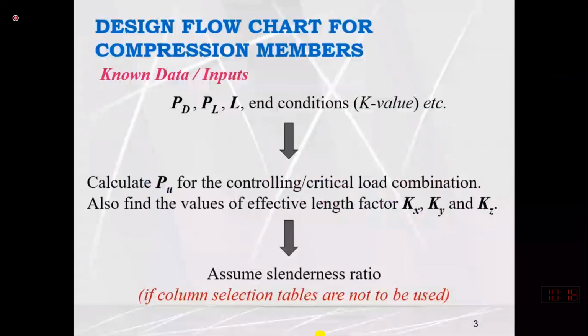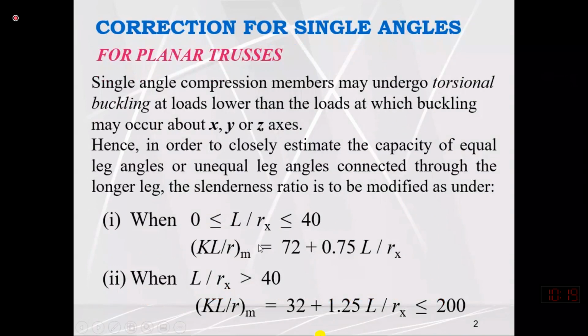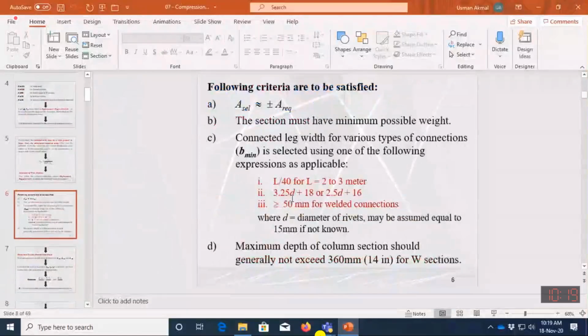What I want to say is that unlike tension member design, where we compute the required gross area from yielding criteria and rupture criteria. In the yielding criteria, we use the yield stress because failure occurs when yielding at the gross area occurs. But in the rupture criteria, we use the ultimate stress value because failure occurs when the applied stress is more than the rupture strength. In this case, it is better to derive the equation again for your understanding.